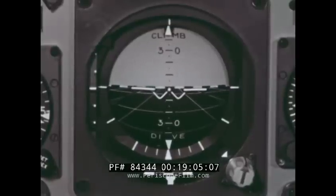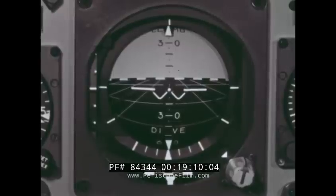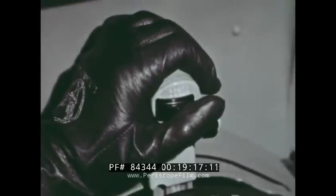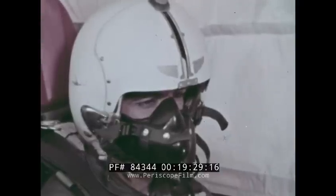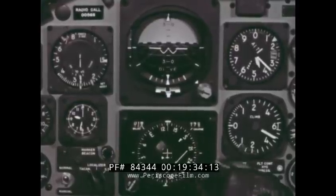Reduce power to 80% and simultaneously lower the nose 10 degrees on the attitude sphere. As the airspeed approaches 270 knots, extend the speed brakes. Maintain your course until reaching the penetration turn altitude.